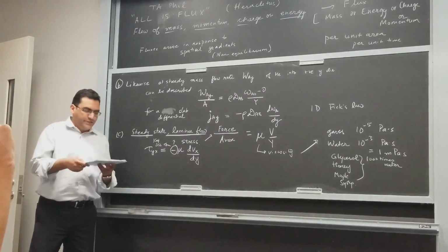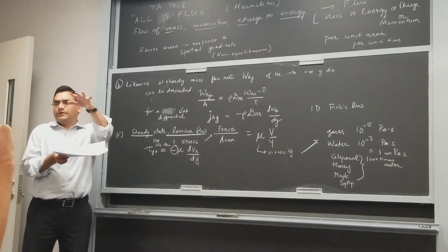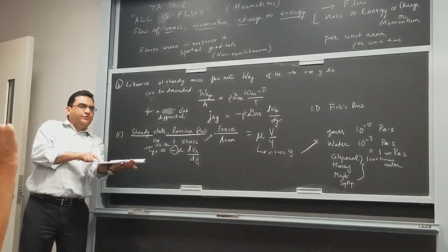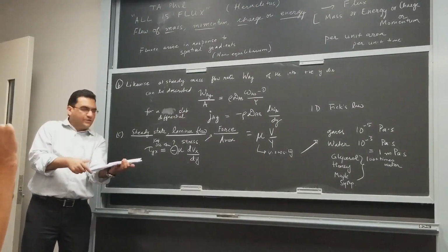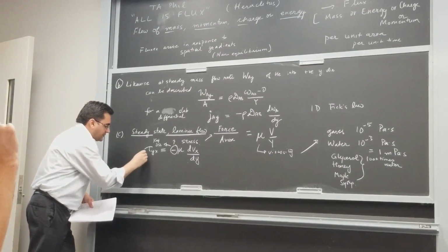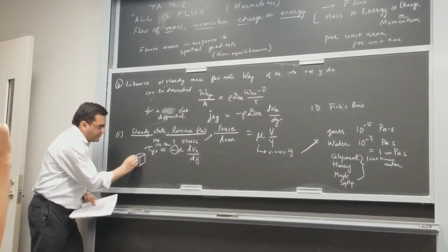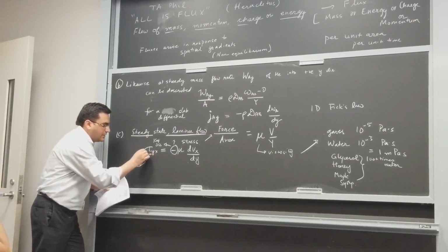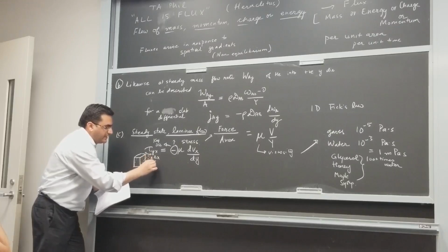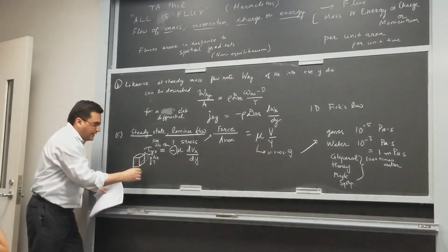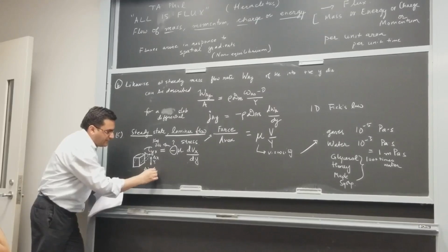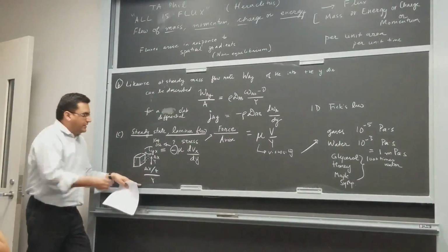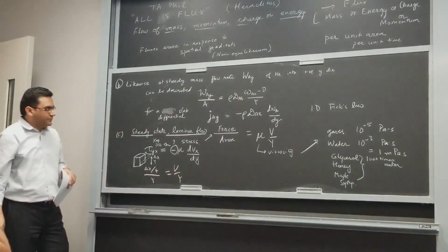We call it shear flow because what shear does is, if I take a cube and I shear it, then the cube is going to get deformed. If I take these sheets of paper and I apply force on the top surface, then it's going to move the top surface more, while the lowermost surface is not even moving. When you apply force at the top, it moves the top surface forward, and this deformation is going to be delta x. If this was y, then the amount of shear you applied is delta x over y. And if I take delta x divided by the time during which I apply this, and divided by y, then if that was shear, this is the shear rate, which is also the same as V over y. So we call this shear rate.